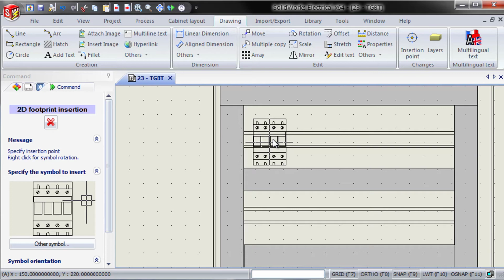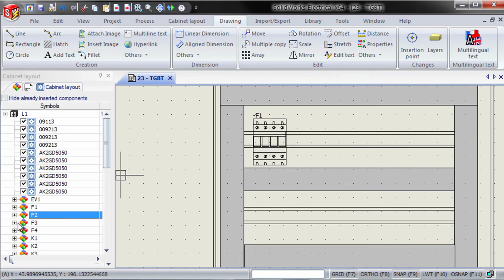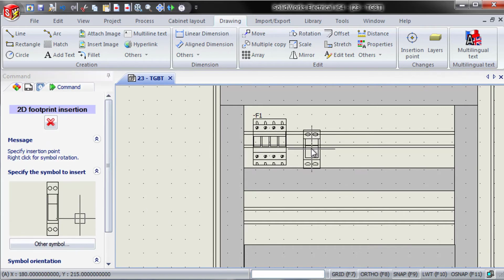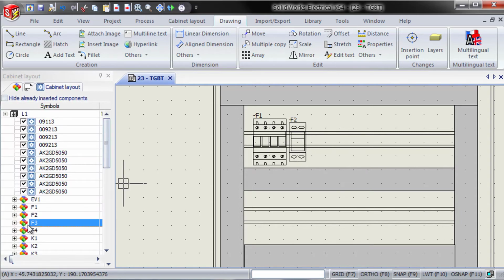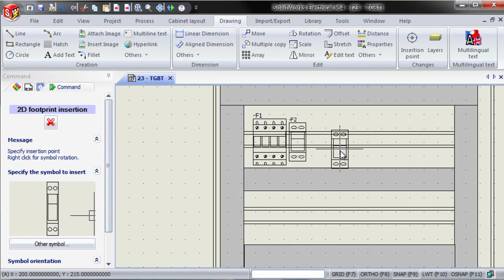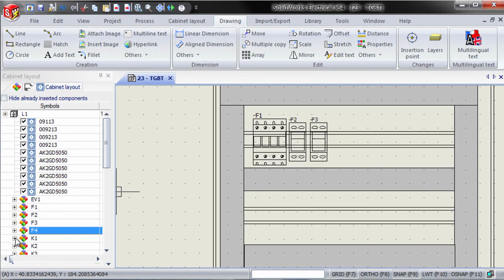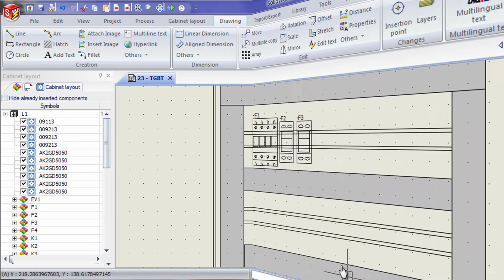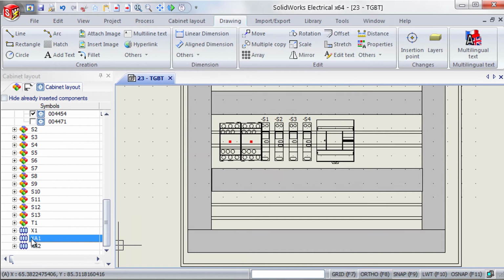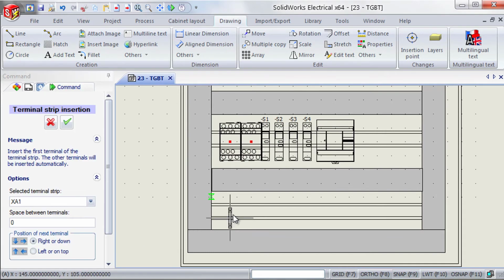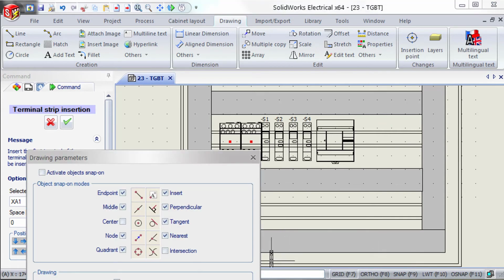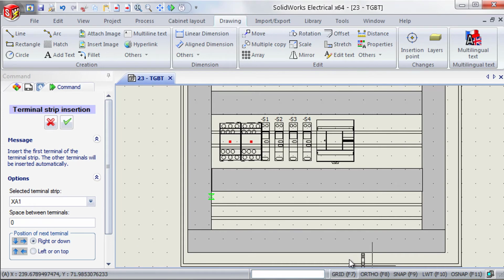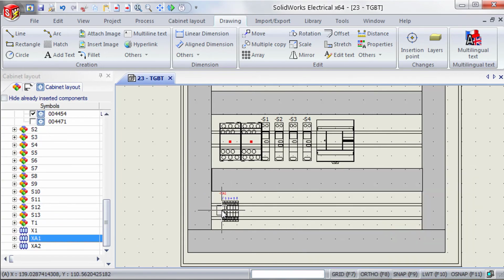All of the shape information is automatically generated after we select the manufacturer part in the schematic diagram. By doing the panel layout, we could get direct measurements of the layout for its components, so it will make sure the dimensions of the box panel are enough for all of the components. For the components which we plan to insert side by side, we could insert them all directly into the box panel and set the space between them.